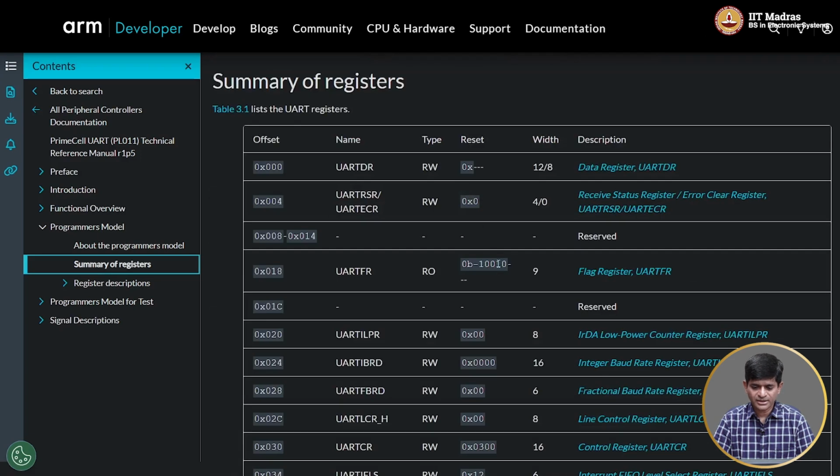And when you go and look at the actual bit locations out here, you can see that in fact bit number 4 and bit number 7, which correspond to the two empty signals, are in fact 1 after reset, but the two in between them, which are the FIFO full signals, turn out to be 0 immediately after reset.